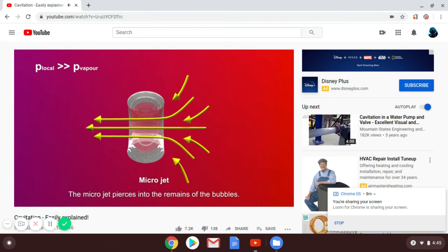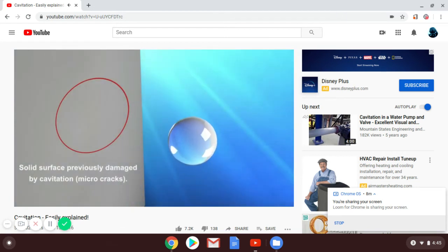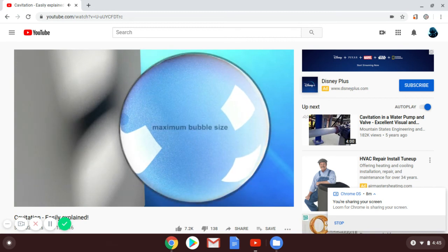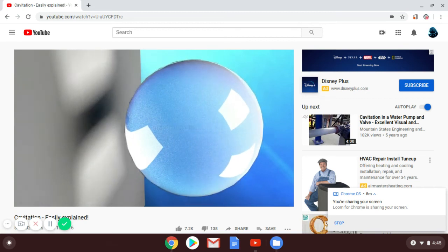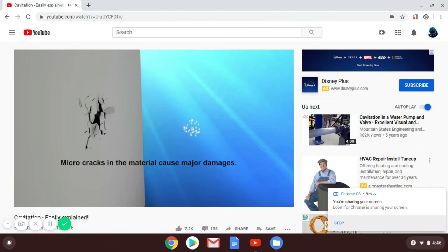The bubble becomes a torus and disintegrates further. The microjet continues to flow in the liquid and can hit a wall. Through its concentrated impact, even high-strength material can be damaged. The implosion releases energy in a very short time, concentrated in a very small spot. If the microjet hits a surface, it damages the material by localized short-term overstraining. The material starts to develop microcracks, and later material can break off.